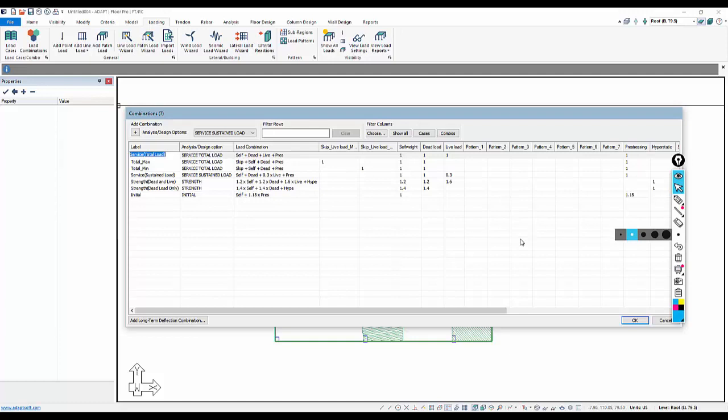And what can happen is if you assign skip max and skip min, and I use these combinations that include those two envelope solutions to evaluate stresses, evaluate actions, evaluate reinforcement on strips, anything pertaining to strips, you essentially could have a situation where the integrated line could include nodal actions and combine them based on different solutions for different patterns. So we want to make sure when we evaluate design strips, we have to actually write a separate combination for each pattern. So this would look something like this.